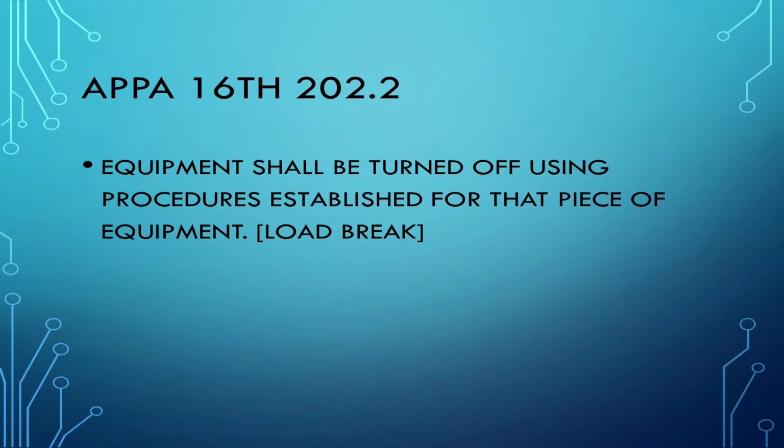Just echoing the previous slide. Is it load break? Is it a switch with what I would call an elephant ear on it, load break? Is it a load break elbow? Is your gang operated switch load break? A gang operated switch with load break on is a lot different than an underslung switch that's used to bypass breakers. That's a perfect example of where you may have to go to the upstream device and make it safe to open or close those switches. Definitely open.